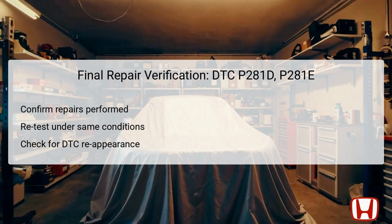Following this, retest the transmission under the same conditions utilized previously, such as shifting from low to drive and keeping it engaged for at least 30 seconds. This method will provide a controlled environment to ascertain if the faults persist. Lastly, check for the reappearance of the error codes. They should not reappear if all repairs were successful, affirming the restoration of proper function to the shift solenoid output circuits within the Honda Civic.